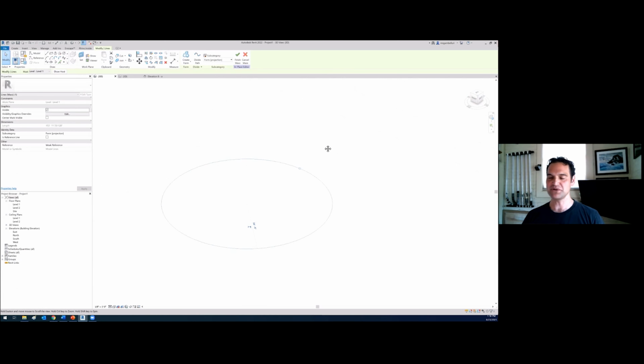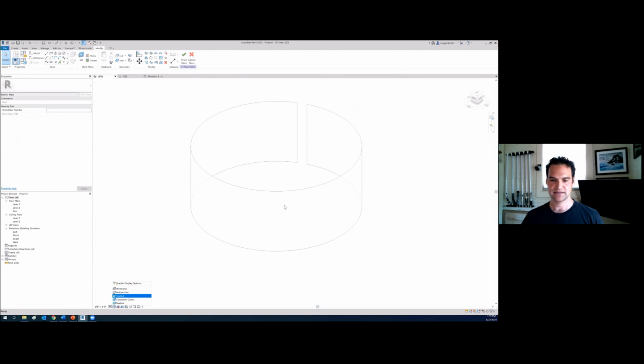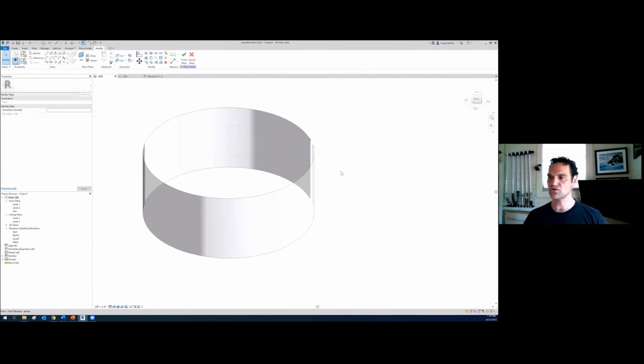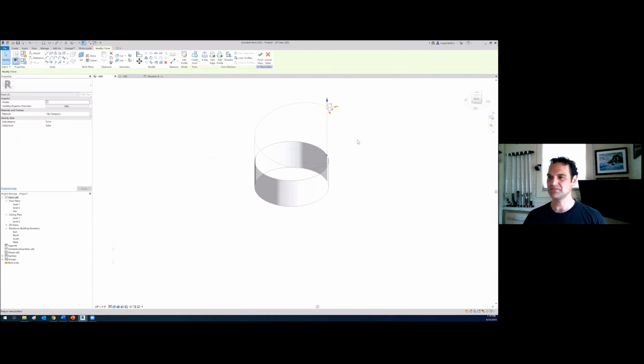Okay, if you want to build a spiral in Revit, get in the massing or adaptive environment, put down a circle really quick. You can just break it like this, okay? And then all you do is you can create a form like this, okay? So here's a form, just an open circle form. You can grab one of the corners and you can just pull it up like that, okay? And then you can grab this edge.